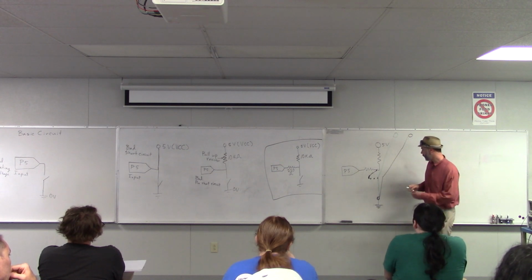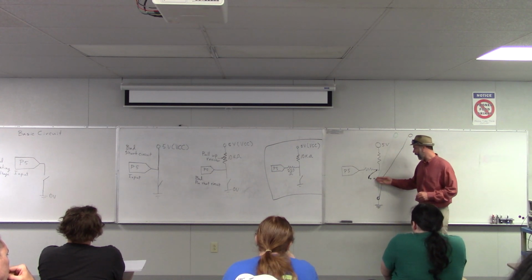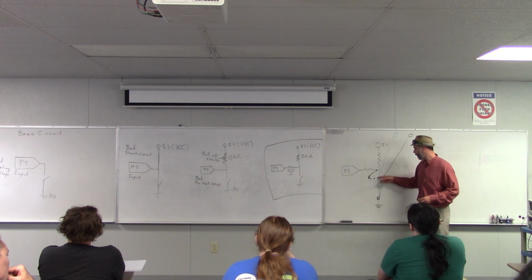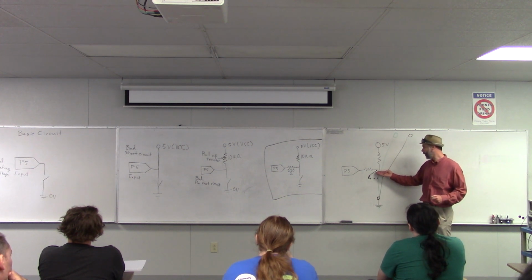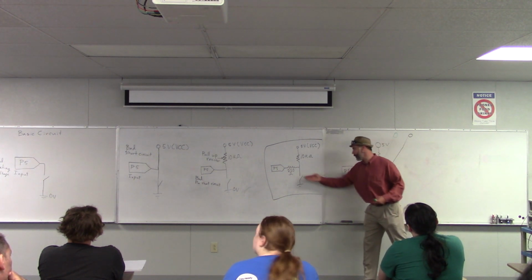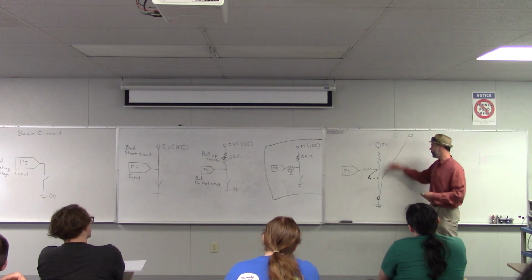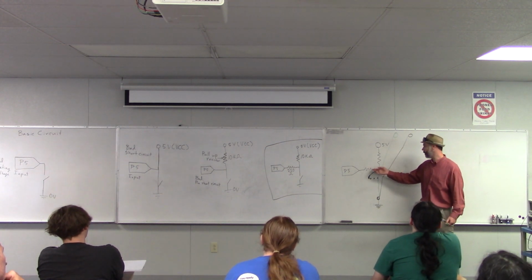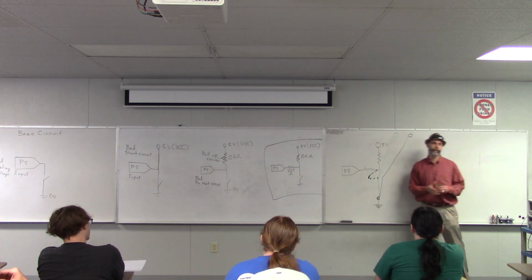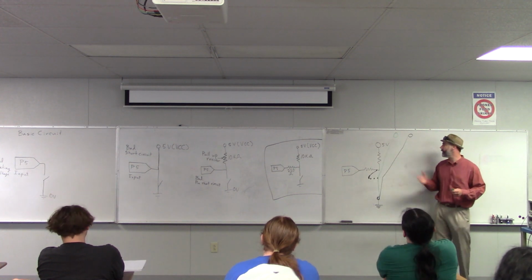So now you've created a connection between this header, this row, this point on the circuit, and ground. That's like when we close this switch. So when you bump into something, this Whisker closes a switch from this point to ground. So what does this voltage now become at the pin? 0 volts, exactly. So that's how it works.